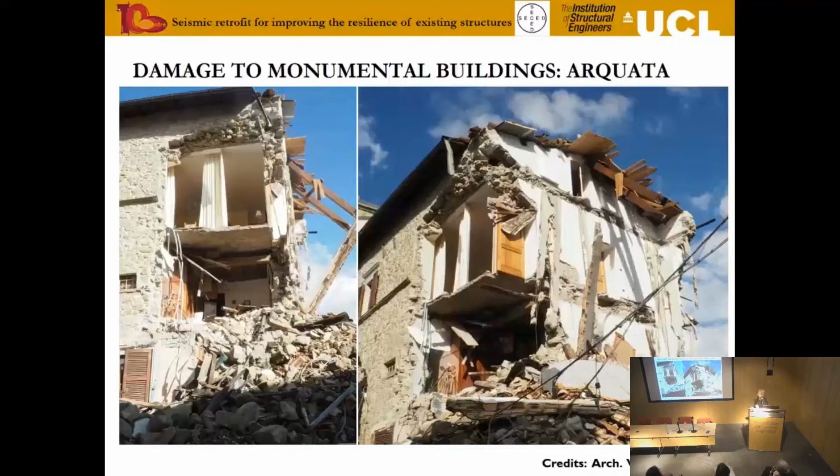There has been some grouting, not very well done. There were a lot of pockets. There have been some attempts at stiffening the floors here by doing a relatively modest concrete slab. Then further up here there is a ring beam and a new concrete floor has been put here.